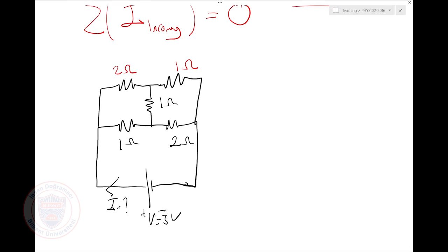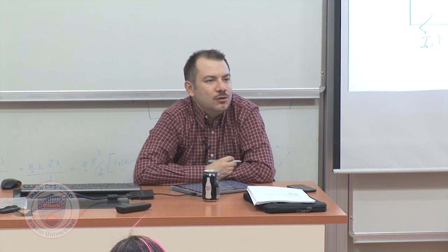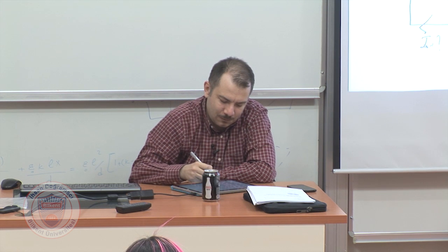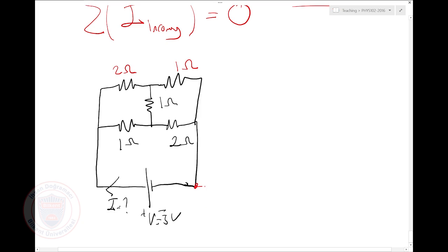First of all, potentials, all potentials we need are relative values, right? So I need a reference point. I can always choose one point in my circuit to be at 0 potential, okay? That's what I'll do. I'll choose one point here, and it's generally shown by this sign. It's called the ground sign. I'll say this conductor is at 0 volts. Well, basically all of the conductor here is at 0 volts, all right?